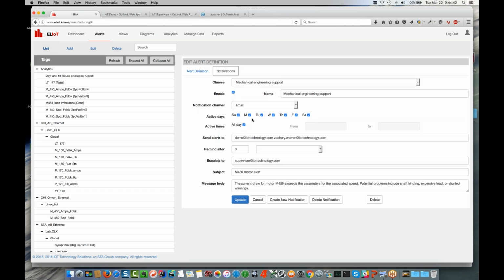Those are common failure modes for chillers. Or things like intermittent failures, like an intermittent proximity switch, where we say, hey, this switch should be closed for a certain amount of time, and when it exceeds that, we've had a customer actually with exactly that problem, where the switch would fail, but then not be a problem later, and they had no way to understand what happened. Well, if we're watching all the timing of all of those activities, we can immediately report the condition, even if the condition goes away.